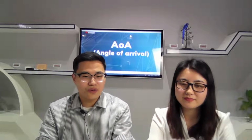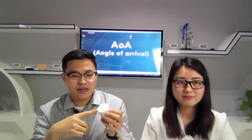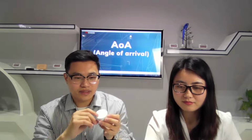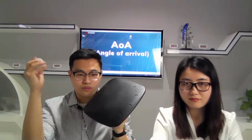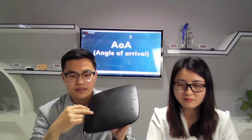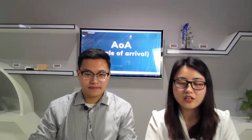So now, you guys want to know how it works? Essentially, we have Bluetooth beacons that are transmitting a constant Bluetooth signal, or you can say a constant tone, or a constant advertising packet. This tone is received by 4 locators over here and the other 3 over there in the room. On the locator side, we have 12 directional antennas arrayed inside this case. There are 4 locators in one set. Each locator has 12 antennas, so the total will be 48 antennas to receive data, right?